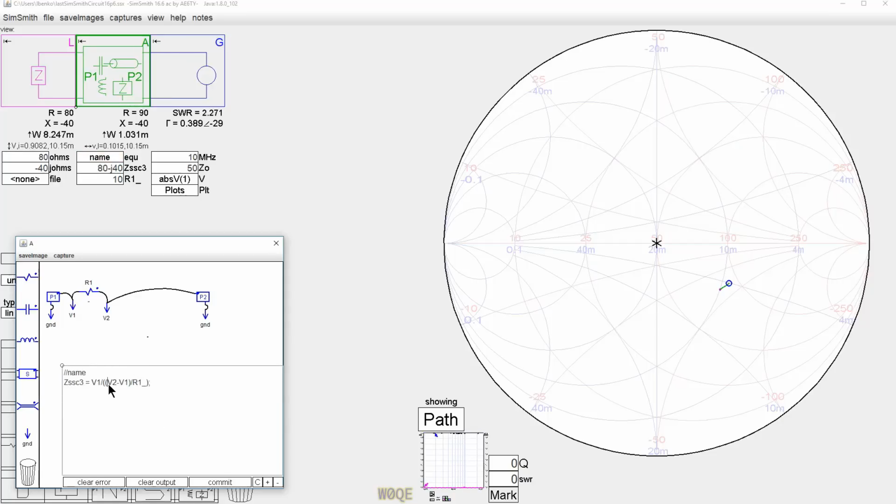So this thing right here is the voltage across the resistor. This is the resistance value, voltage divided by, not the resistance value, it's an impedance value. This could be R1, it wouldn't have mattered. R1 could have been 10 plus J5, it wouldn't have mattered. Voltage across this component divided by the impedance of this component is the current, and then we're going to use the voltage going into our device under test, which is still left here.